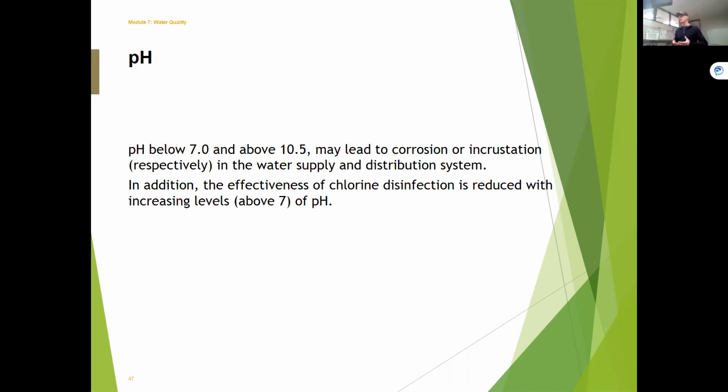So keep that in mind. But unfortunately, when pHs start to come up, the effectiveness of chlorine doesn't work as well anymore. There's something called ORP, or oxidation reduction potential. What ends up happening there is that chlorine effectiveness, or how much acid and ion, we talked a little bit about that with disinfection, will change depending on pH.